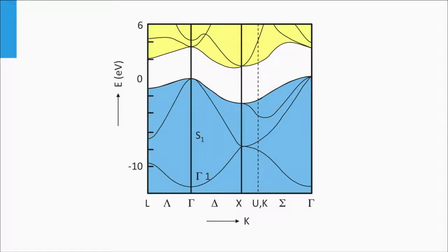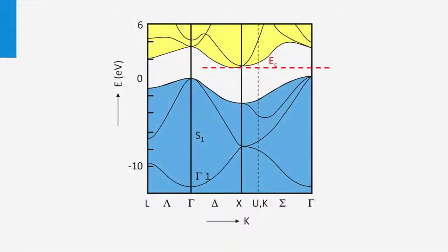The white area reflects the energy levels in the forbidden band gap. The horizontal axis reflects the lattice momentum in various directions. The band gap of silicon is determined by the lowest energy point of the conduction band at X related to the 100 direction and the highest energy value of the valence band at gamma.